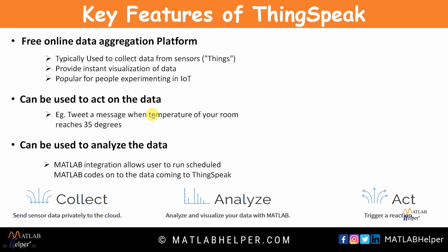An example is that I can tweet a message to a person when the temperature of a room reaches 35 degrees. Suppose my room temperature reaches 35 degrees and I want to get an alarm. I can get a message from ThingSpeak, and it can be used to analyze the data. MATLAB integration allows the user to run scheduled MATLAB code on the data coming to ThingSpeak.